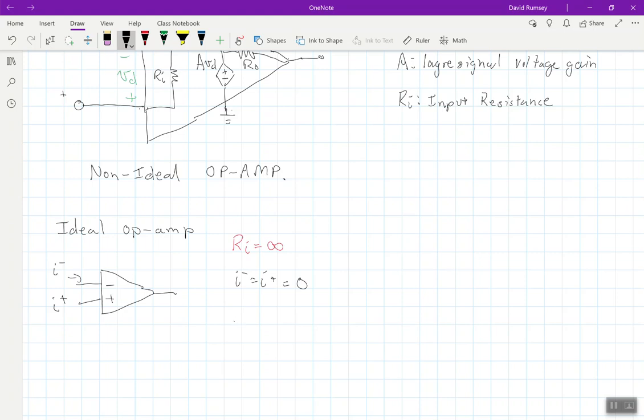The other thing that's going to be important for us here is that our large signal voltage gain is also infinity. We're going to assume that it's infinity. We have as much as we want. Again, we see that it's not infinity on the 741, and there are op-amps with a much higher large signal voltage gain, but it was still around 200,000. Of course, everyone says 200,000 is not even close to infinity, because you could do 2 giga or whatever. But the point is it's really large, so we let it be infinity because it makes our circuit analysis a little simpler when we're dealing with op-amps.